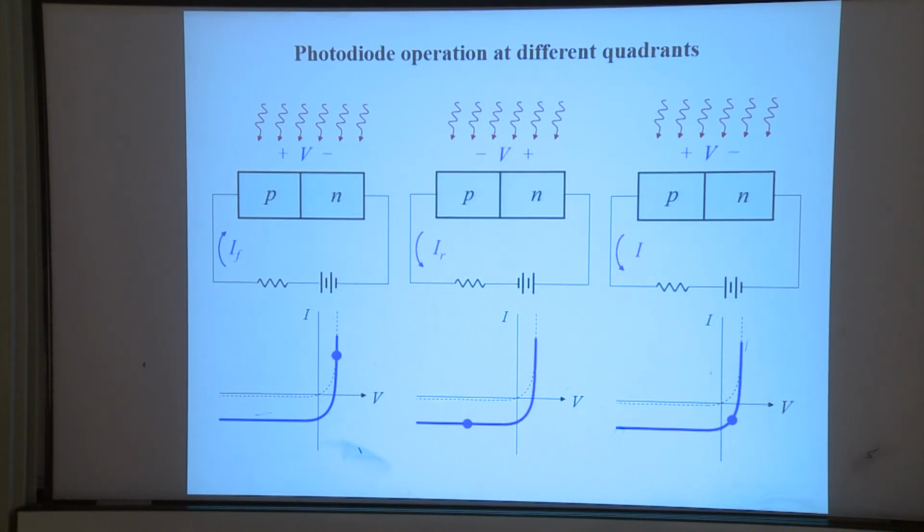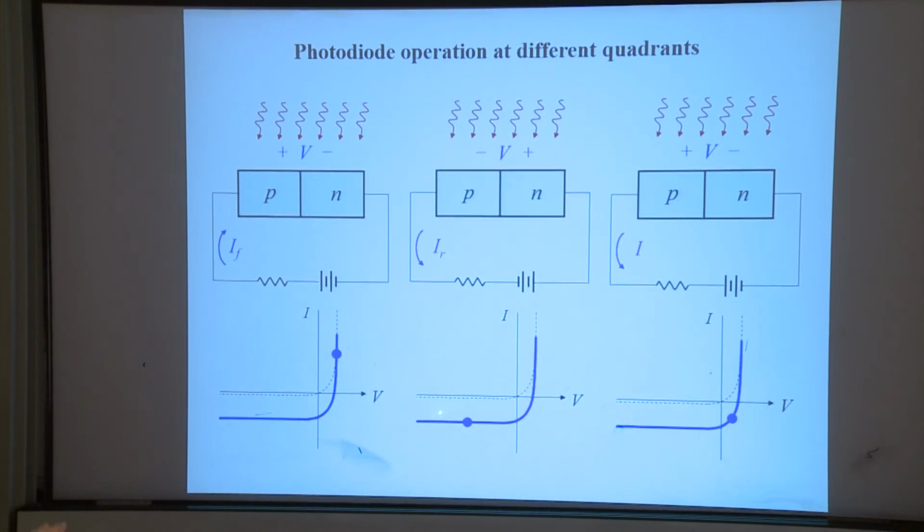As long as you reverse bias a little bit away from zero voltage, you always get a constant current, and this current is a function of irradiance, sure, in the negative direction. But actually, negative polarity is defined by humans. You can always regard it as positive, even though we draw it here as negative.